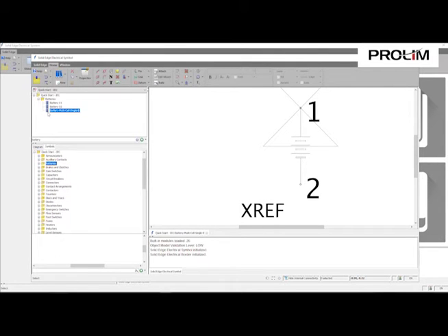So if I go ahead and click this, I've got the batteries folder open here. If I just right click on this battery, I have the option to click new symbol right from here. So I know that it's a battery, it's a part of the IEC, or maybe whatever library you're in. If I know I want to create a battery and it's going to be in this folder, I just right click, say new symbol, and I'll step you through this. So first we're going to give it a name. We'll say it's a battery test 03.